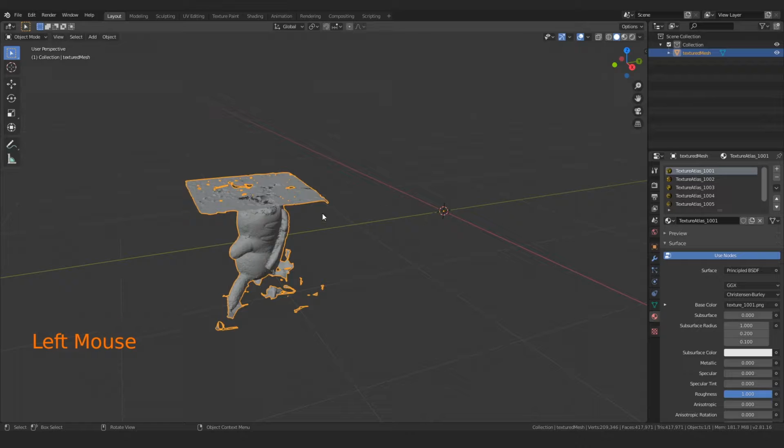We need to keep in mind that there is actually a point here which denotes the center of the object, which is exactly why Blender brought in the Pikachu plushie offset. It's because the origin or the pivot point of the object was offset when Meshroom created it for some reason. There can be a number of reasons for this that I'm not going to get into, because it could be any number of them. It's a really complicated thing. So what you need to know is that every object has a pivot point or an origin point. Those are the two words you'll see used to describe it.